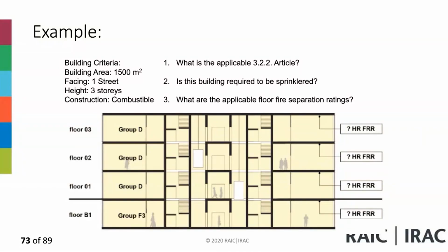Okay. So that means that if I have a kitchen on the ground floor and the upper floors will be residential, there's no separation as long as it's subsidiary. As long as the residential occupancy. Yeah. But then there are specific provisions that you need to look at for the floor area and separations of corridor service, service areas and service spaces. So there are provisions related to that, but they are not major occupancy separations.